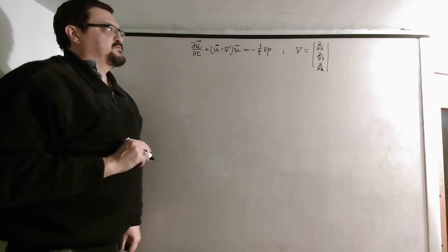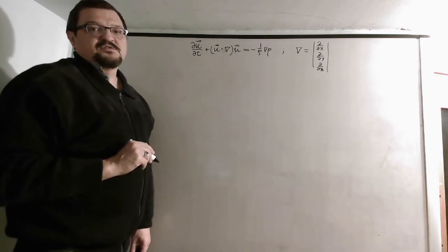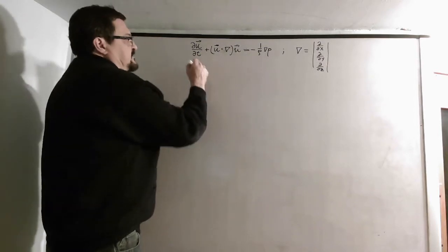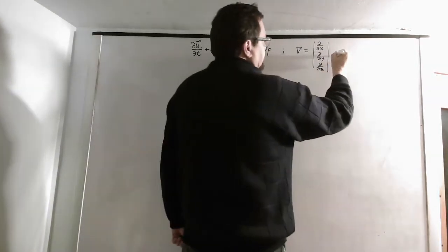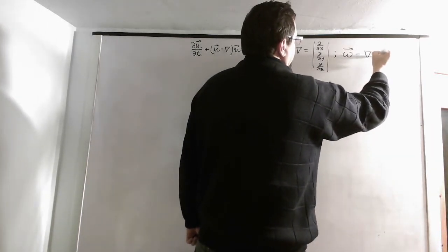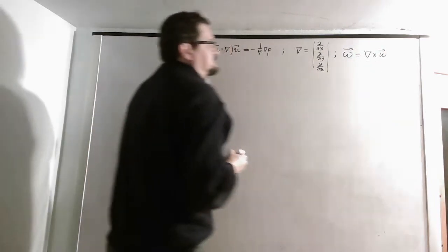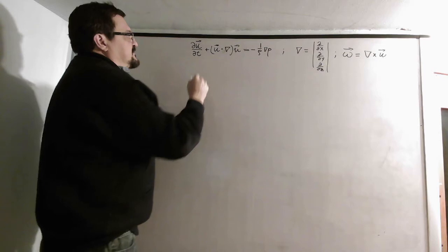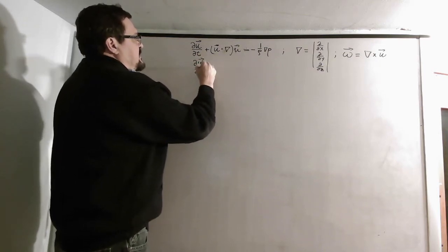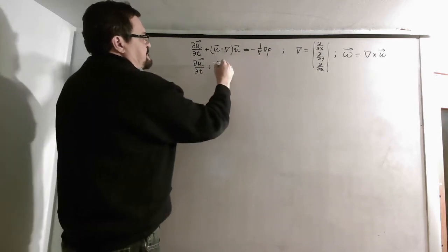You also know from your dynamics class probably that the same equation can be written in the so-called vector-invariant form involving vorticity. If we define vorticity, you know that the vorticity vector equals the vector product of this del vector and the velocity vector. So you can then write this same equation in vector vorticity form like that.